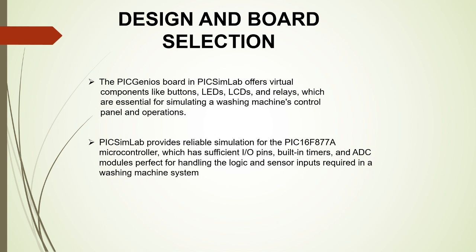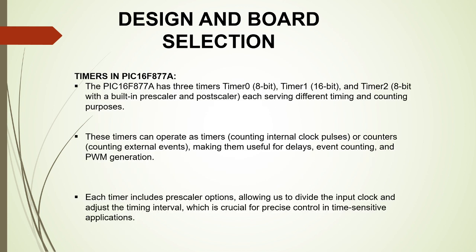and it offers visual components like buttons, LEDs, LCDs, and relays, which are essential for simulating a washing machine's control panel and operations. PICSimLab provides reliable simulation for the PIC16F877A microcontroller, which has sufficient IO pins, built-in timers, and ADC modules, perfect for handling the logic and sensor inputs required in a washing machine system.